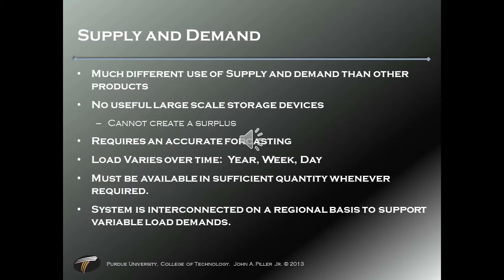What do I mean by that? We need to define what the load is going to be at any given time. But the fact of the matter is that that load varies over time. Over time of the year, there is a different amount of load that's demanded on the grid for summer, winter, fall, and spring. Over the week, there's a different amount and type of load that's demanded Monday, Tuesday, Wednesday, Thursday,